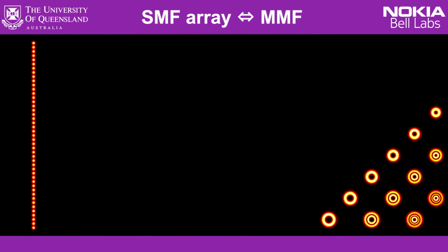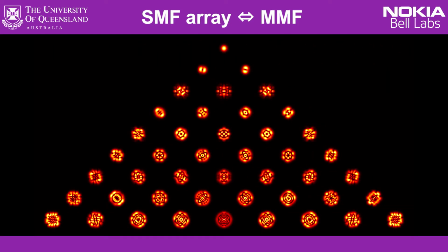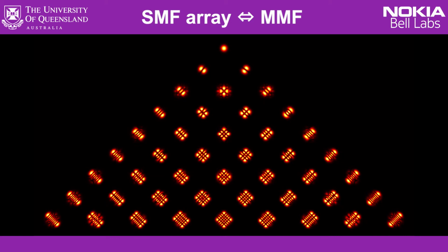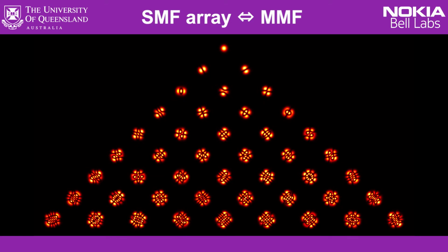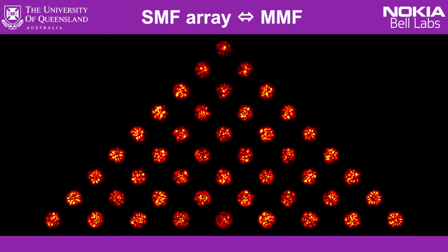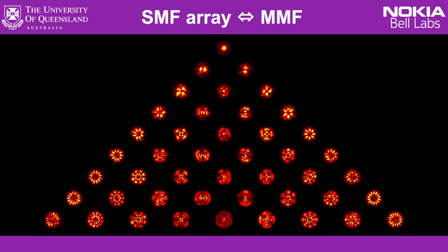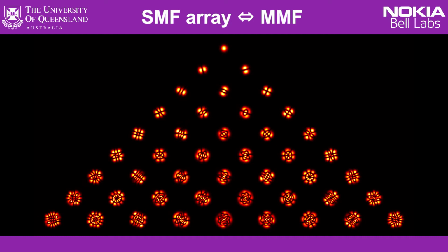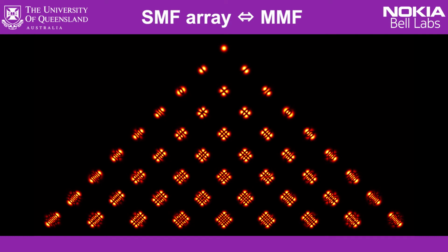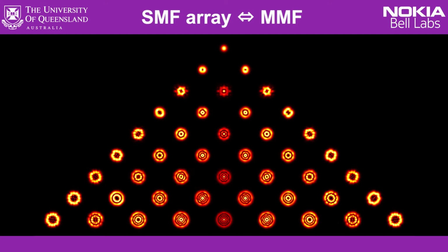We also generally don't care what orthogonal set of modes the single mode fiber maps to. It could be something like Laguerre Gaussian, which closely resembles the fiber eigenmodes, but it could also just be a complete scrambling of modes. Astronomers don't care what the mode mapping is, and in telecommunications we generally don't care either, because over long lengths of transmission fiber, the modes are going to couple anyway, regardless of how you put them into the fiber in the first place.